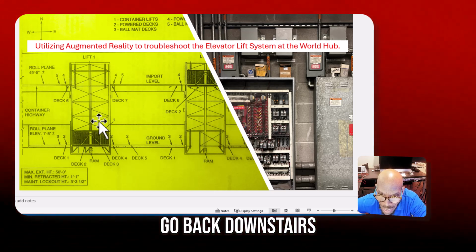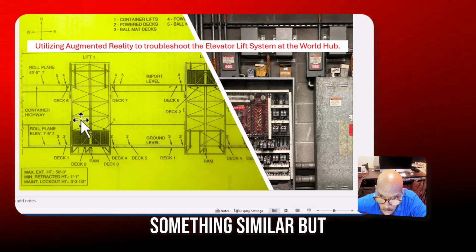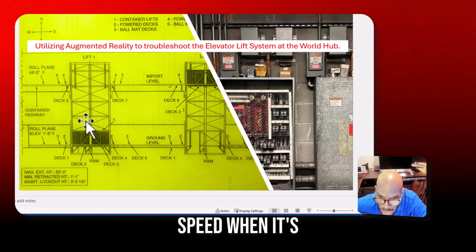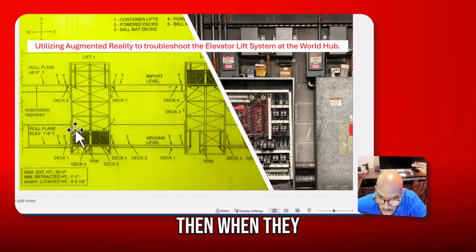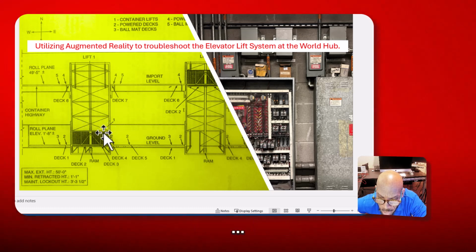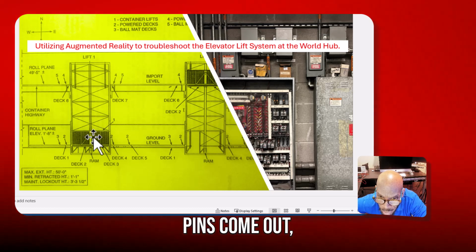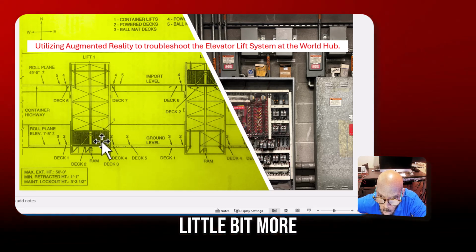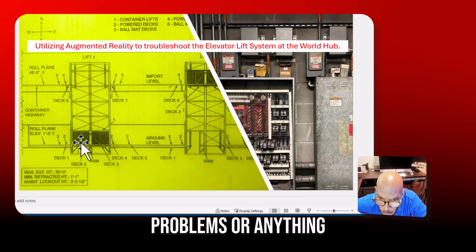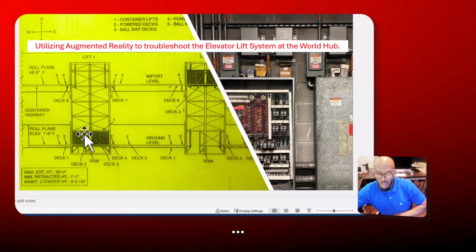When they go back downstairs, it's going to do something similar, but it's going to go into a fast speed when it's coming down here. Then when it gets somewhere in this area right here, it's going to start slowing down, and then it's going to almost stop, and then the pins come out, and then it goes down a little bit more and rests on the pads. If there's no problems, then the doors are open and the containers will come out.